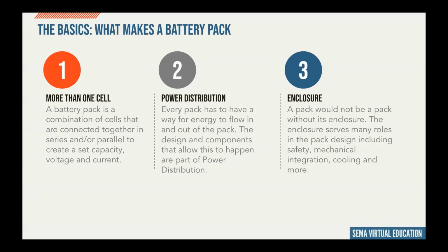This is just how we see a battery pack, is that a battery pack typically has more than one cell. It is a combination of cells that achieves essentially a certain capacity in kilowatt hours, a certain amperage capacity in amp hours, and a specific voltage for a system. So it has those three defined elements to it and is typically made of more than one cell. The other thing that we look at that defines a pack is power distribution. A battery pack without power distribution is a module, and therefore not a battery pack.